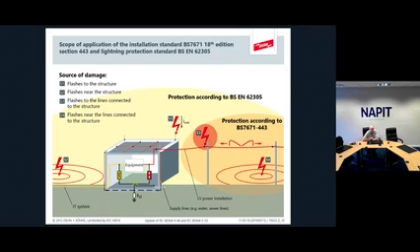Your job is to basically plug the holes in the Faraday cage, which is the cables coming from the outside into the building, and you do that by using SPDs. So we're only interested in 7671 regarding surges down overhead lines or buried cables. But the overall standard 62305 is, as I say, the main document, and a lump of that has been taken out and dropped into 7671, firstly 443 and then 534.